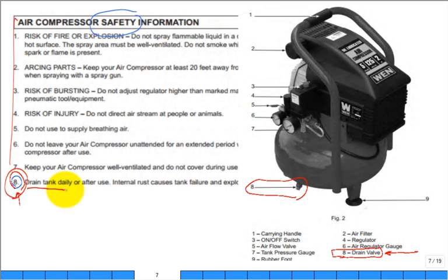Drain tank daily or after use. Internal rust causes tank failure and some like explosion. I think I truncated it. So what's going to happen if you don't drain your tank? You get rust. And it could lead to tank failure.